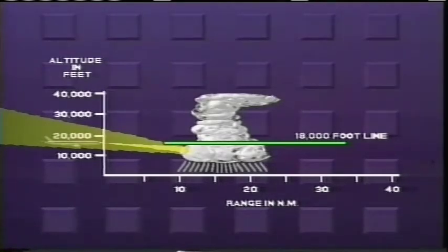If you ever find yourself in doubt about whether or not the tilt position is correct after you have made a range change, move the tilt angle down briefly and readjust the beam to give the correct amount of ground return. The best way to develop good tilt and range management skills is to practice them in good weather. Once you have gained these skills and refined them, it will be a simple matter to properly adjust the tilt and range controls for safe weather avoidance.